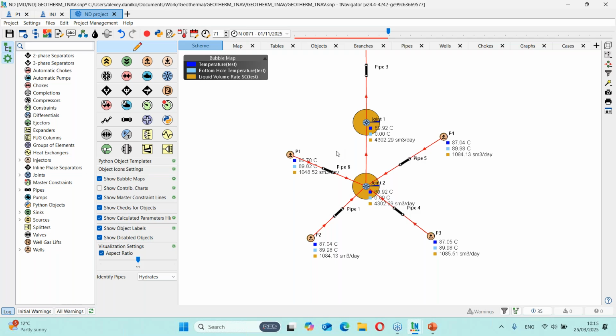So we can have a look in very fine detail at the description of the pipeline, and we can select the heat transfer coefficient, and play with it and see what is the optimal heat transfer coefficient to deliver as much of the heat as possible to the production facility. And instead of specifying a heat transfer coefficient, we have much more advanced options for the description of the pipelines.